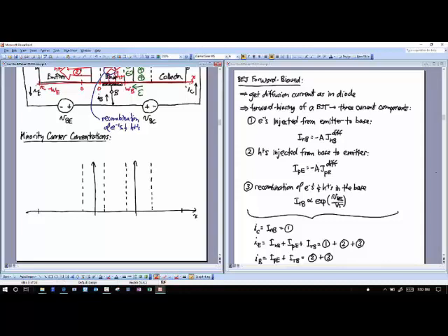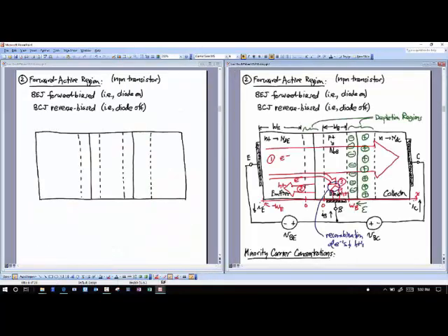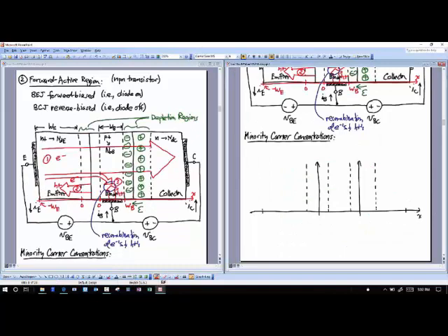So, yes? Real quick, so if you didn't have a voltage source there, would they just cancel out, or what was going to happen? Voltage source where? Anywhere, if you just disconnect all the voltage sources. If you have no voltage sources, you get no current flow. Because the voltage source, what it does is it generates a large amount of minority carrier. So let's talk about that right now. So just this voltage that I put across the base to emitter junction, what's it doing? If I look at this now what I'm going to plot is the minority carrier concentration here. And so let me label this.